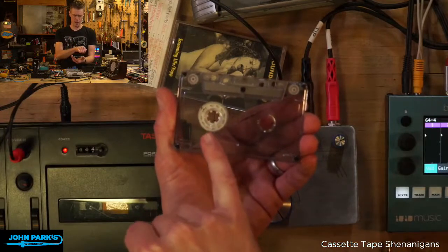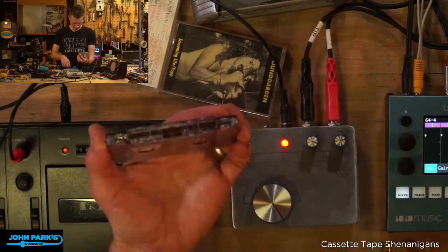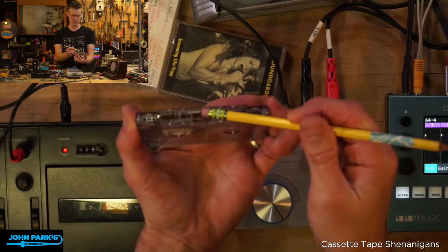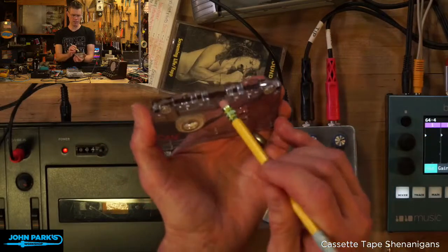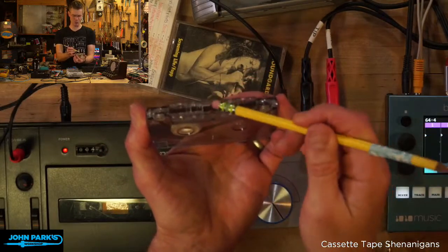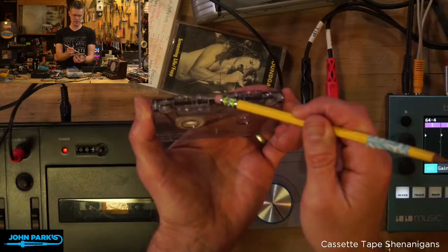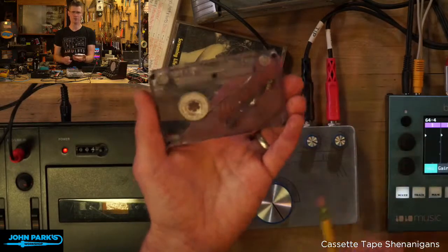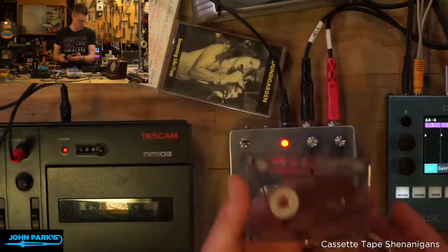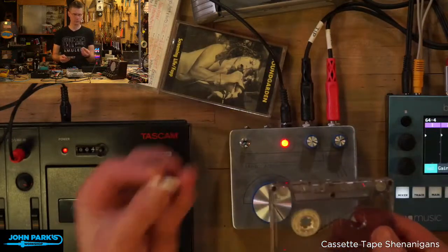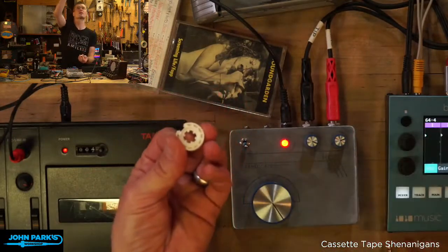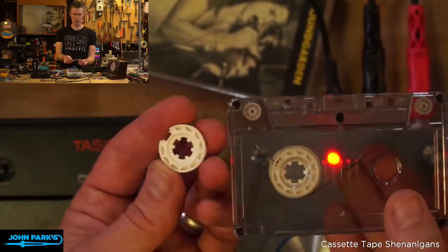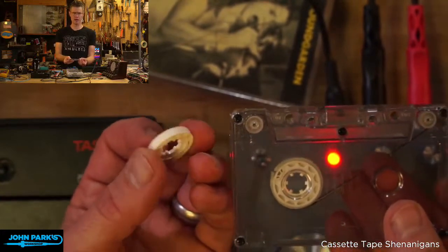And the other trick with these is the amount of tension. So when a tape head presses against the tape, it pushes it into this little felt doodad here, official term. You need to make enough contact there, so this can't be stretched so tight that this doesn't depress in. It also can't be so loose that the take-up reel there, which is just a little piece of plastic like this, slips. Let me zoom in a little closer and focus better on these things. So that on its own is quite slippery, not a lot of friction there.